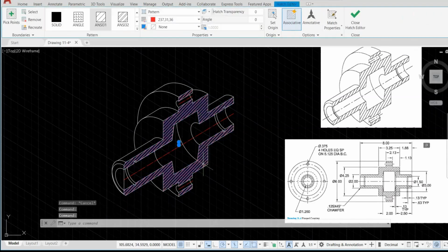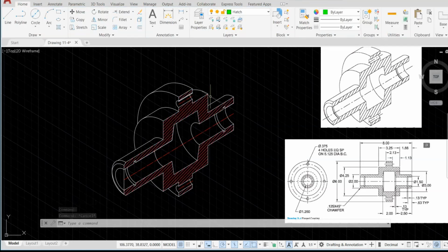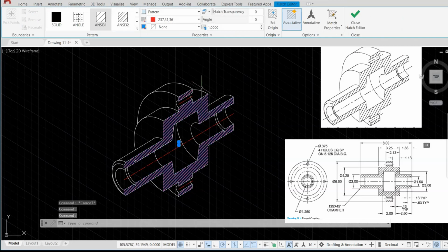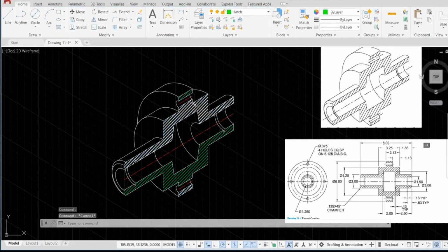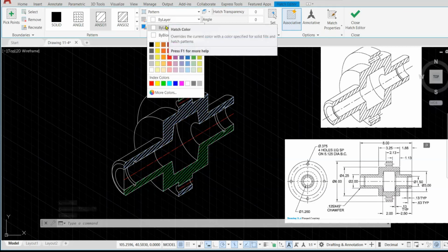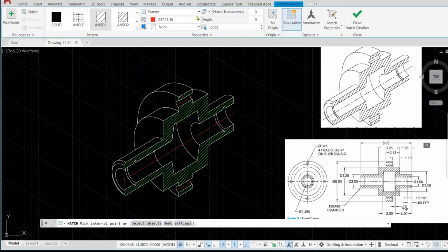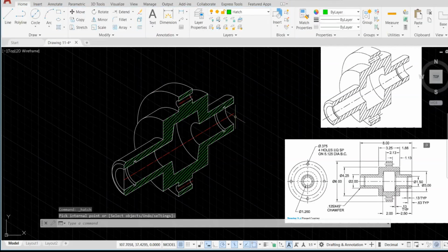And this one should be drawn on the hatch, so be sure here to get them to the correct layer. Be sure there is no override or something. I always recommend leaving everything to bilayer. Okay, so here you go. Just make that as well, as it should be bilayer. Okay, so everything, make sure it is bilayer. Then you close the hatch creation.